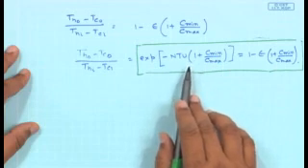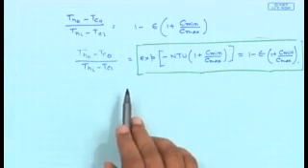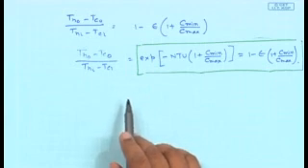So this is the beauty of the Epsilon-NTU method, starting with a simple definition of epsilon, and applying it for the case of a parallel flow heat exchanger, 1-1 heat exchanger, in which C minimum is taken to be equal to CH. By making simple statements, heat balance, definition of epsilon, definition of NTU, we have arrived at an expression that contains only epsilon and NTU. And what is NTU? NTU contains the overall heat transfer coefficient U.